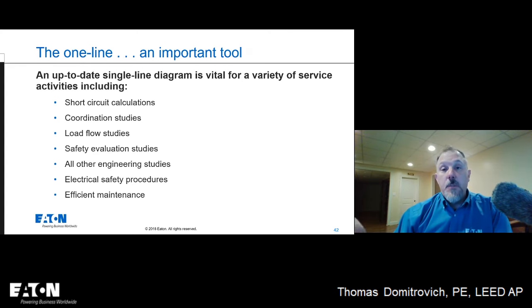If there's anybody in the best position to do that, it would be your design build contractors or your engineering firms. If you reach out to your customer and build a contract around their power distribution system, in such a manner as to say, look, we're going to maintain that one-line diagram for you, we're going to keep it updated, then with any changes, you should be doing an arc flash analysis study and a short circuit study. If you have a lot of harmonics and harmonic drives, or if you've installed filters, you're going to constantly need to make sure that your power quality analysis is up to date. You don't want to create series resonance and other issues because you're changing the power distribution system.